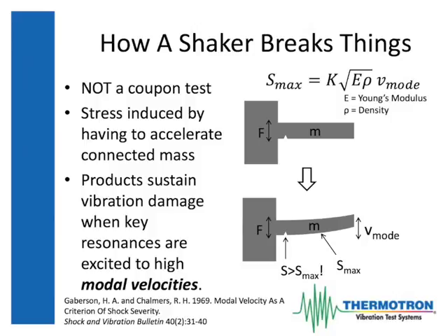So products sustain vibration damage not when they are simply pulled too far, but when key resonances within the product are excited to high modal velocities. Now I've quoted a paper there, Howie, Gaberson and Chalmers, which is a fairly old paper at this point, citing modal velocity as a criterion of damage, and the equation is up there in the top right.